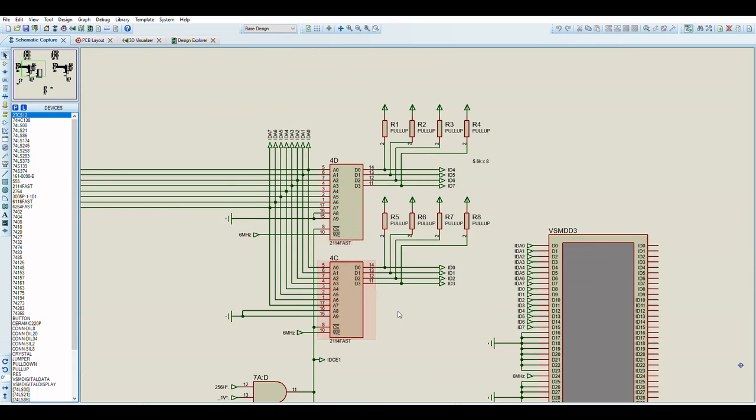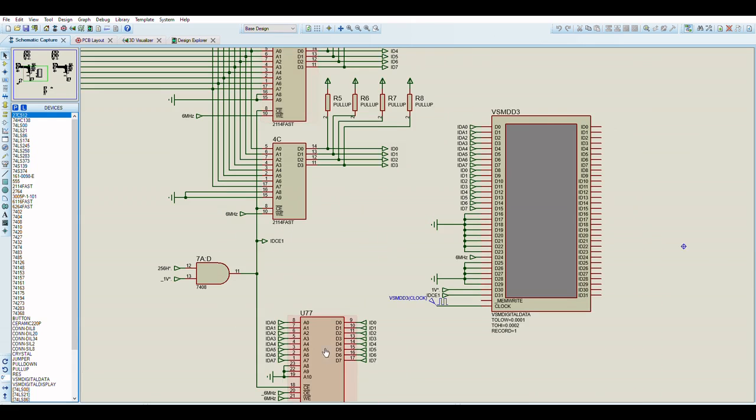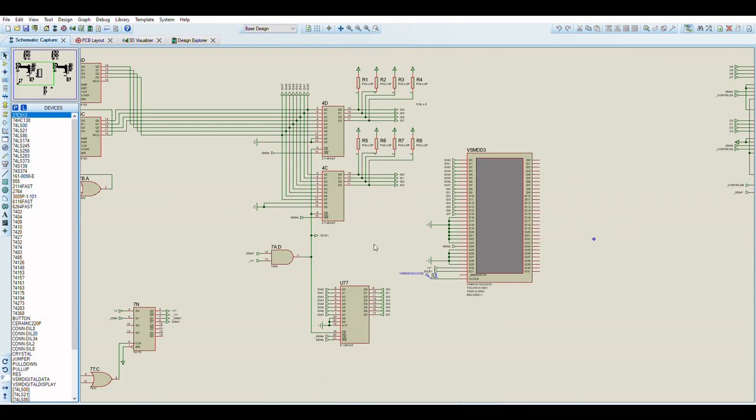It will first read, and then it will flip to a write enabled mode, and then just after it outputs a pixel down here, it will then use these weak pull-up resistors to set FF back for writing back into the RAMs here, or because this is also connected to the same output, then the weak pull-up resistors will set FF back into this RAM and it will be written back.